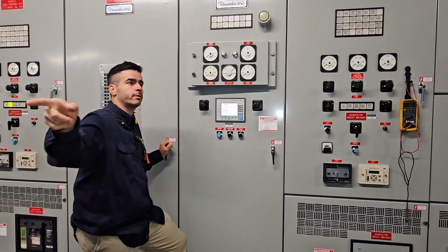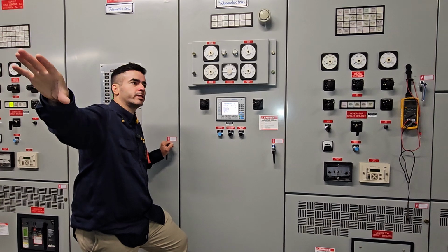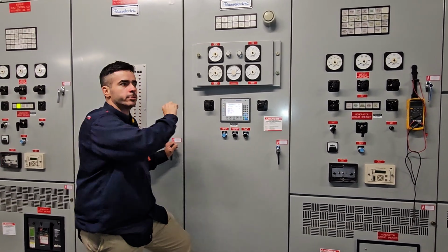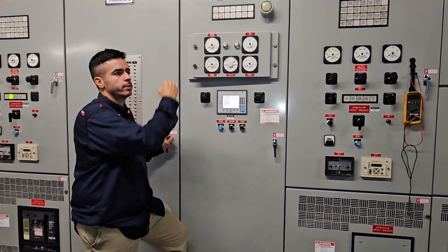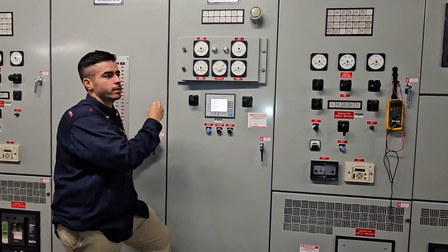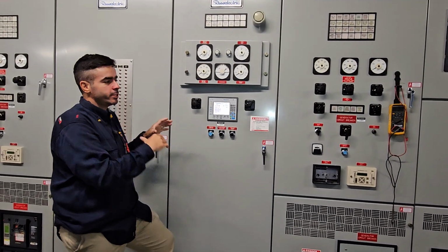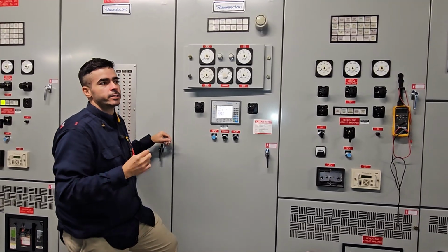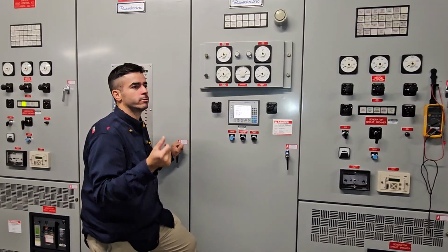Like these guys, they are all open transition. So if you transfer these guys, you'll hear, okay, generator power is over, boom, you see the red light there, and then you'll hear boom, boom. So it opens, and then it closes. And those guys, you hear a boom, that quick. It's because you don't see it, but it closes on the second source and then opens the first one. But it has 300 milliseconds to do that. That's why you hear it so quick.